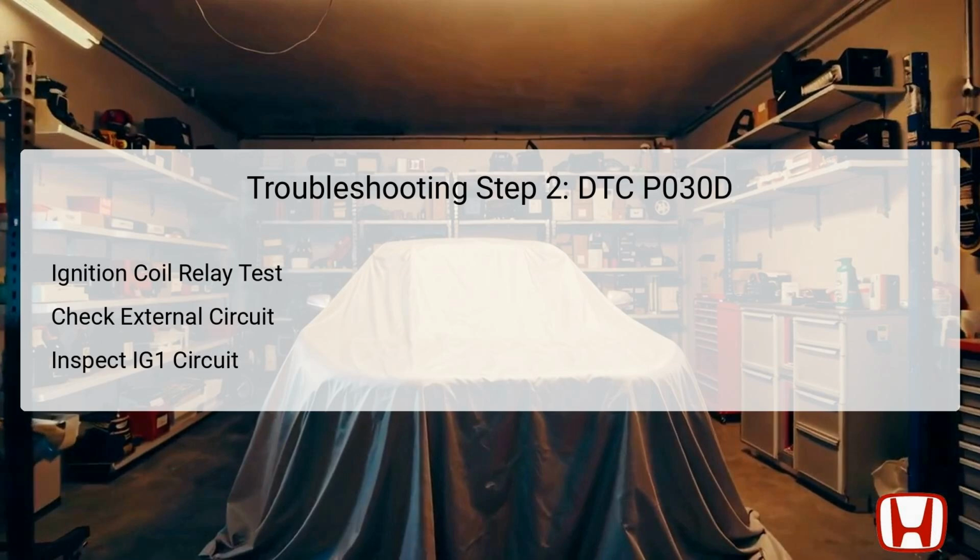This relay serves as a critical component that supplies power to the ignition coils, ensuring they function properly. After confirming the relay is functioning correctly, the external circuit should be inspected for issues such as damage or corrosion that could impede electrical flow.